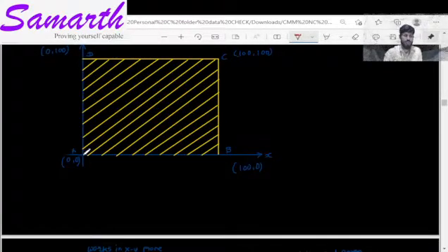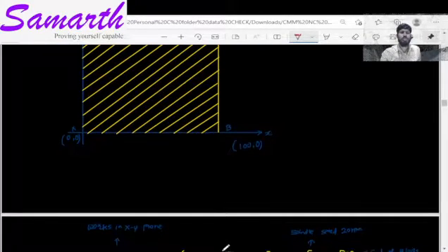This is here 0, 0 and the Z coordinate is 3. That means somewhat away from this 0, 0. If we take the Z axis towards me, then the screen is the XY plane. Then 3 mm from the screen there will be a Z point, Z coordinate equal to 3. There the tool will go rapidly and stop.